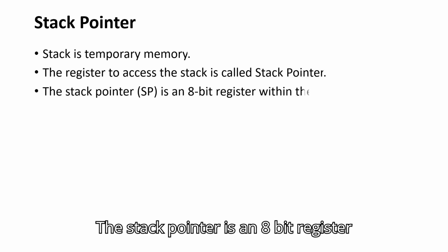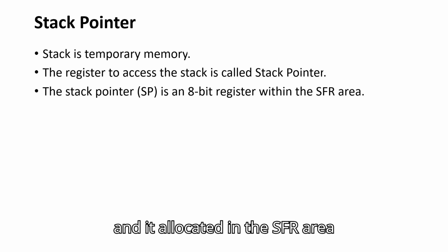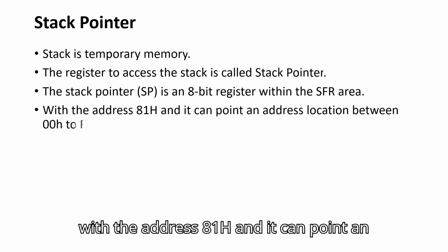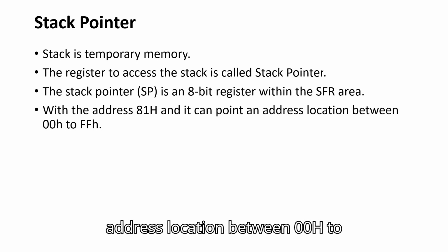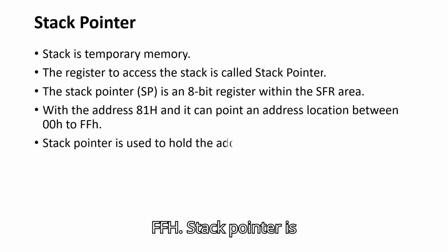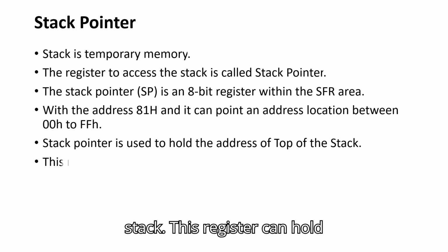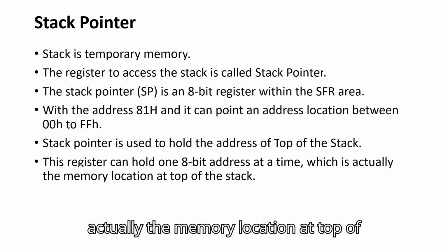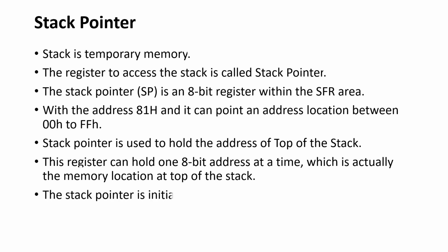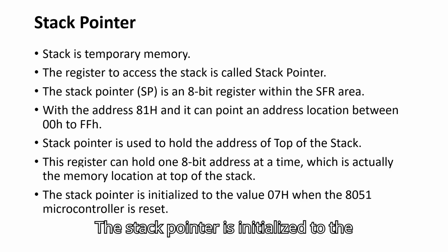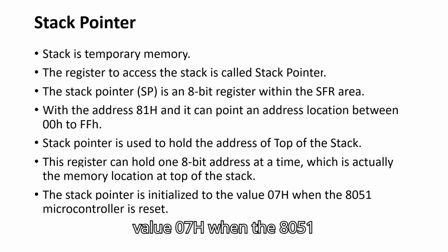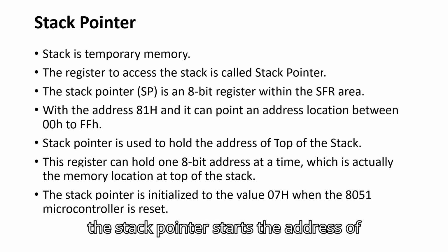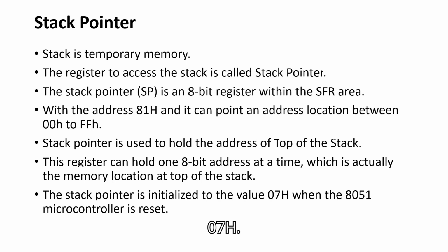The stack pointer is an 8-bit register and it is allocated in the SFR area with the address 81H, and it can point to an address location between 00H to FFH. Stack pointer is used to hold the address of top of the stack. This register can hold one 8-bit address at a time, which is actually the memory location at top of the stack. The stack pointer is initialized to the value 07H when the 8051 microcontroller is reset. That means whenever the microcontroller is reset, the stack pointer starts at the address 07H.